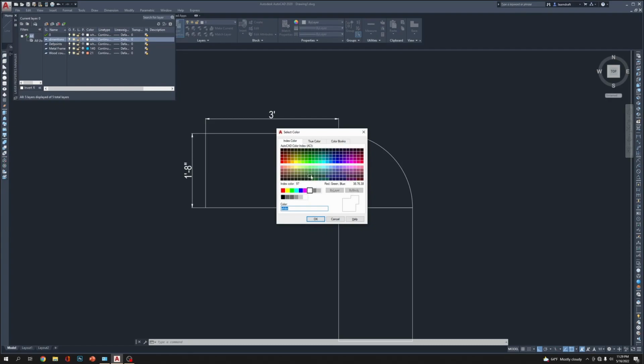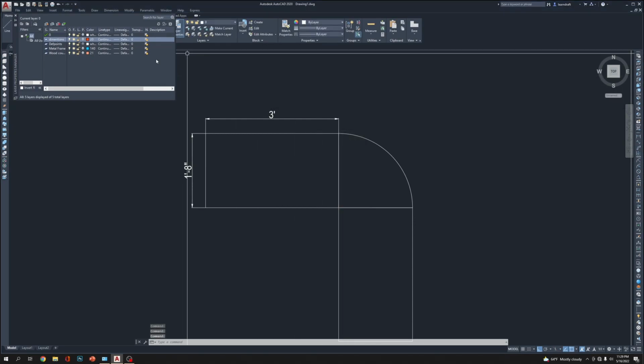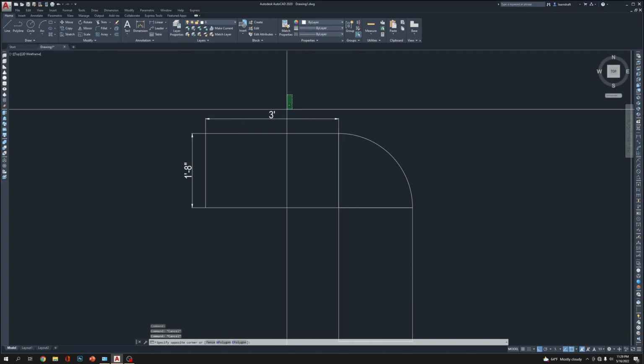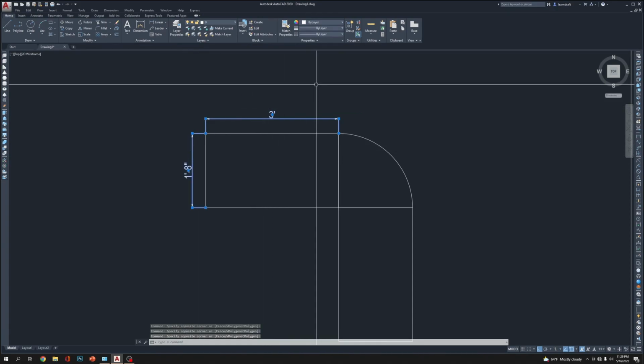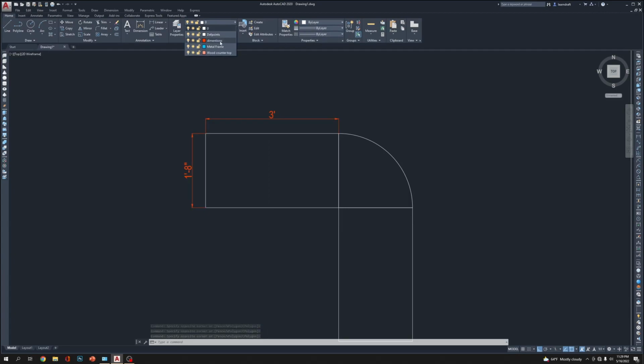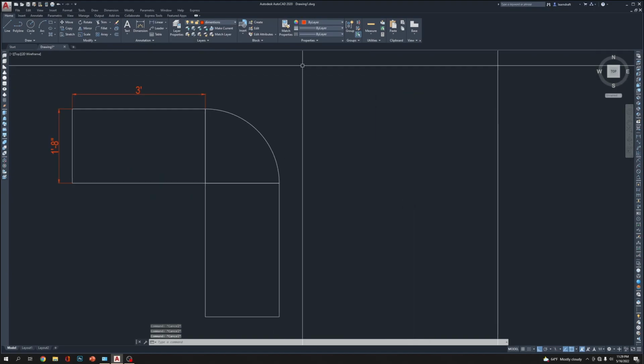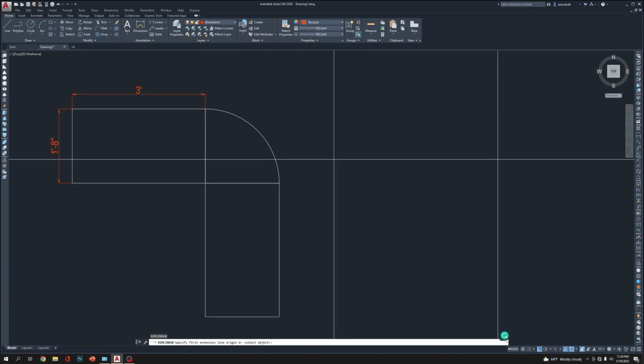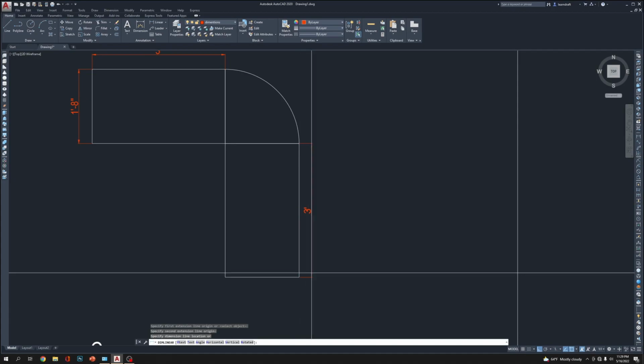Make it color like yellow, no, yeah, this color is going to be more visible. Alrighty, I'm closing it up. I have selected both lines, going to go to the dimensions, and then actually I'm going to select dimension from here, DLI, enter, from here to there.